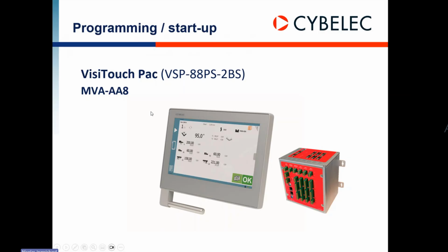The controller for this machine will be a VisiTouch pack, 8 axes, and MVA AA8. So MVA is this little module that has I/O, digital, analog, and the encoder feedback here. And the VisiTouch pack is the main controller with the CPU that has the software and the HMI for the customer.